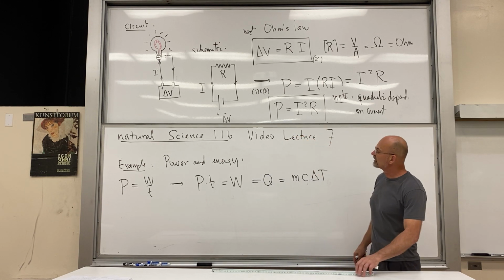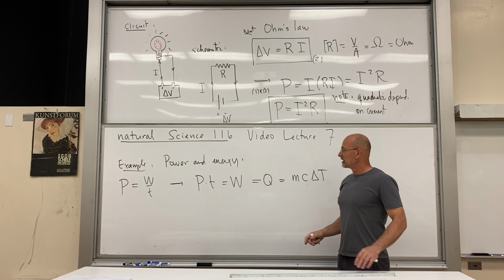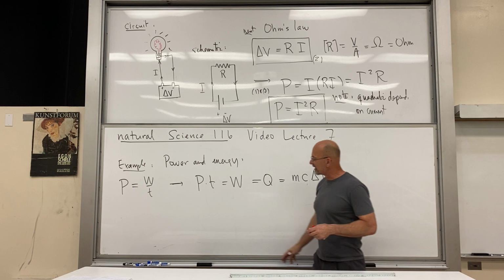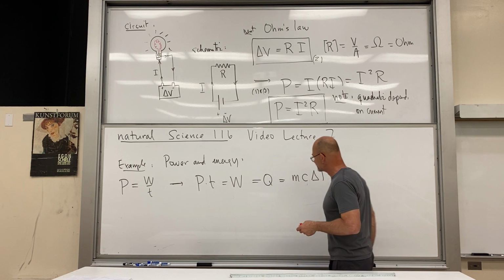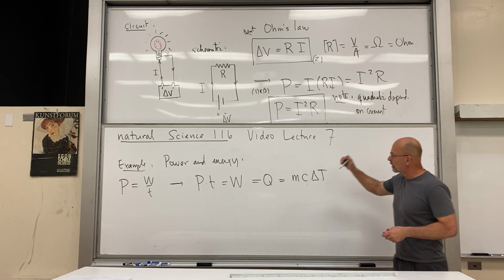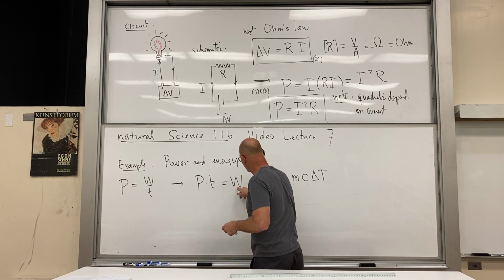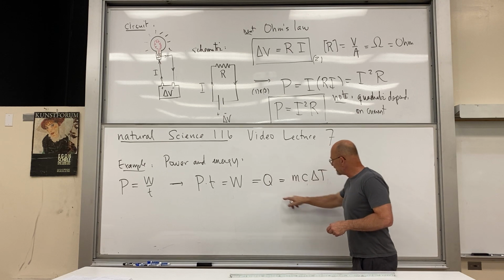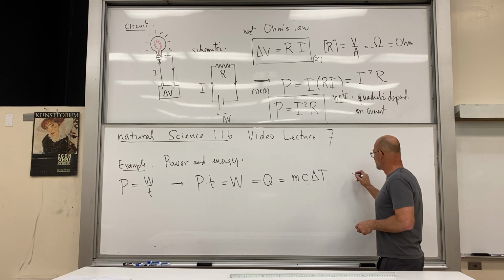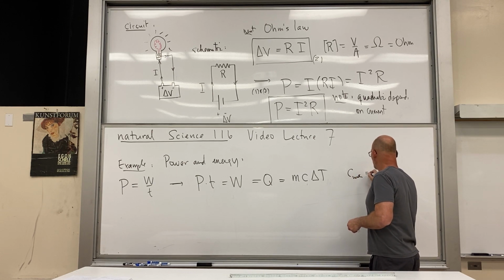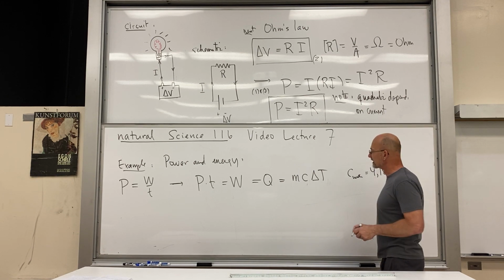Okay. So if we're heating something up, there's our circuit, maybe we're boiling water using electricity, then the amount of energy that we're interested in is how many kilowatt hours it is, because we're going to convert that to dollars and cents. So this is a good formula here to do some homework problems on. Power times time, that's energy. If it's thermal energy, then we have the mc delta T formula from heating things up. Okay, remember, specific heat of water was 4,186 joules per kilogram degrees Celsius.